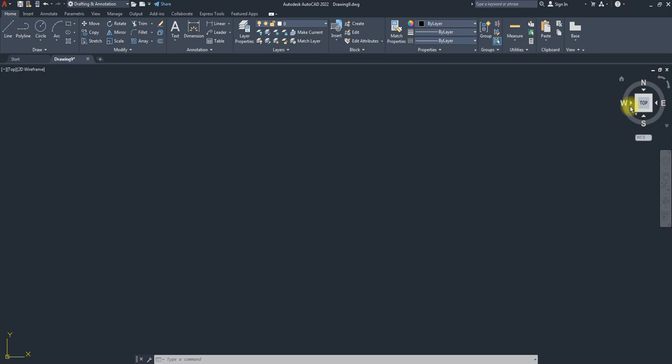Alright? So that means when we are doing that L shape, we started with our world coordinate system 1. When we shifted this to here, we had our user coordinate system 1, then we shifted to user coordinate system 2. So every time you shift your graph, you are getting a new user coordinate system. Alright? It's very important.